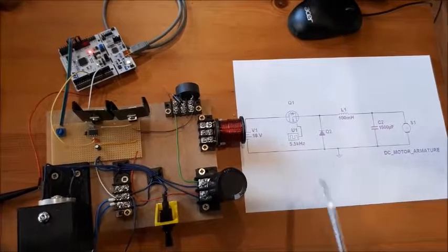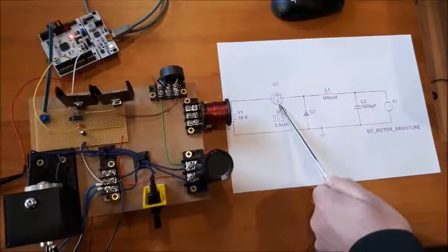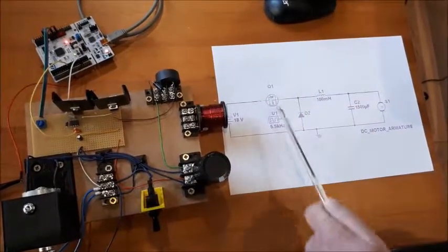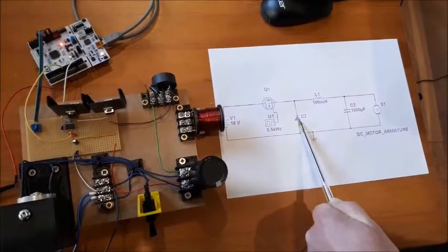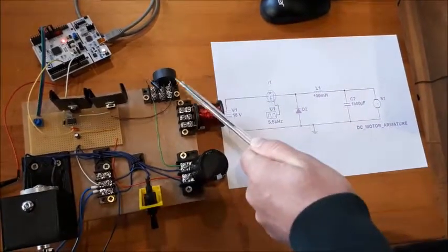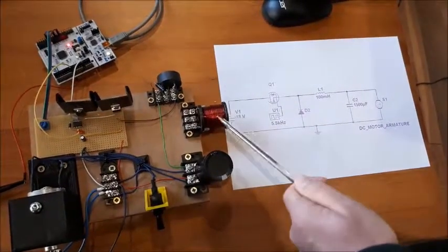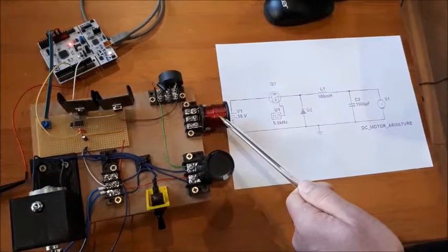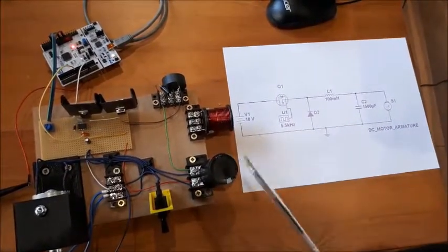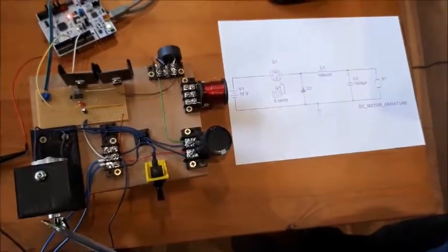Okay, and back to the circuit diagram, just to point out the components used. This is the MOSFET in our circuit. MOSFET, diode, Schottky diode, inductor. We've just so happened to have the 100 millihenry connected in circuit, but we have used the 560, which can be seen in the report. It's disconnected at the moment. Capacitor, 1500 microfarads. Capacitor, motor, which is our load in this project.